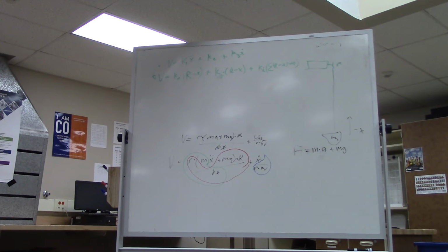You said it works better with filters. Are you talking about a Kalman type filter? Or a state space observer, or you could do lead lag, or there's a whole bunch of them. Yeah, you have those filters and frequency filters. On 971, we have a couple of Kalman filters in there, but it's a lot more math to explain to people, so I don't like to recommend it. We could be here all day with controls math, which is a lot of fun, but yeah.